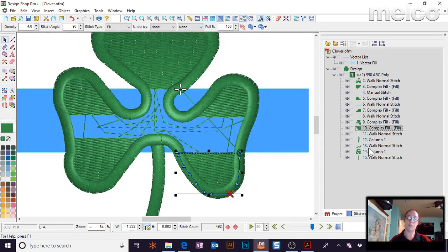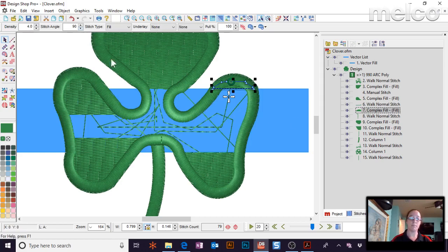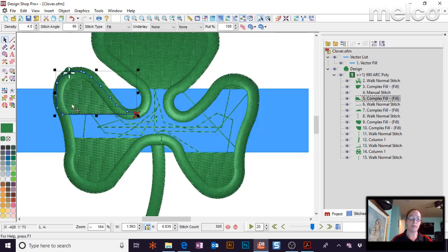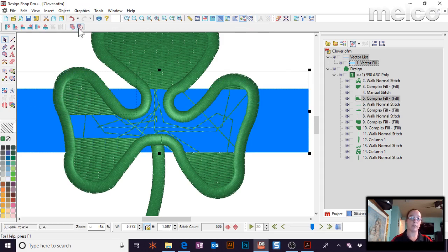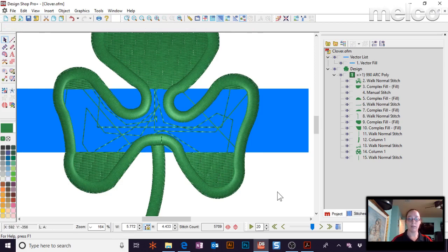So you can see by using that subtract elements, it's a faster operation and you don't have to eyeball where it intersects. So again, to do subtract, select the shape, hold the Control key, click on the vector. Then up here, subtract elements. That leaves just the top. Again, select the shape, select the vector, subtract elements. Okay, really quick. All right, so that was there.